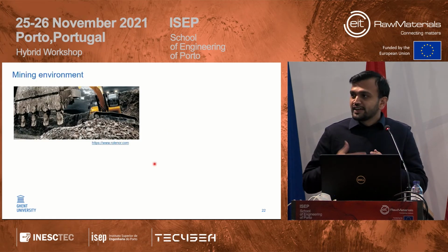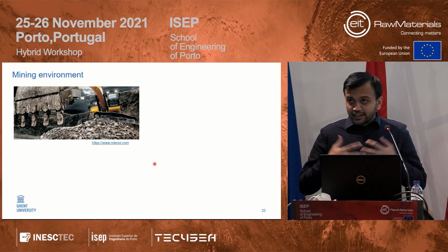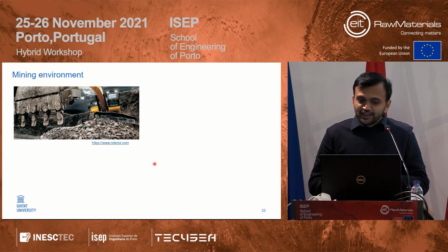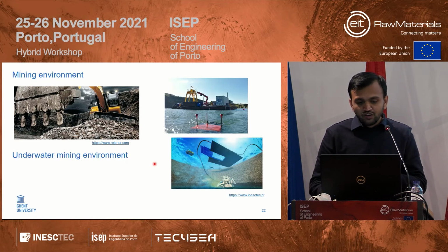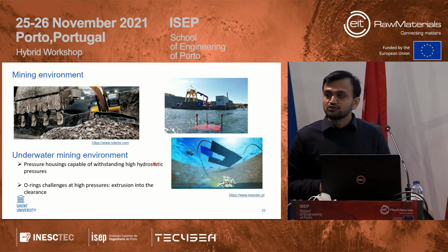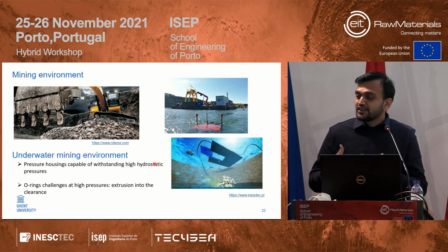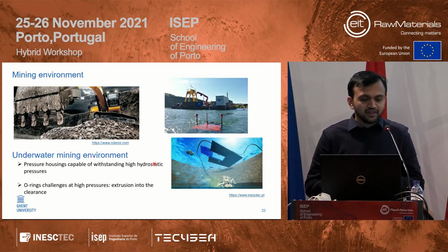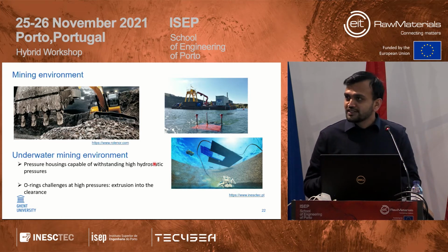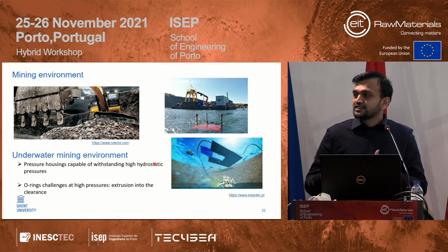Now, for each and every application, the conditions where we are going to introduce our components are different. In a mining environment, like earth mining or underwater mining, there are two major challenges in underwater mining: the pressure housing, or the materials which go under high hydrostatic pressure. And the second one, sealing the entire mechanical components, is also a high challenge because of the O-rings that will go under extrusion into the clearance.